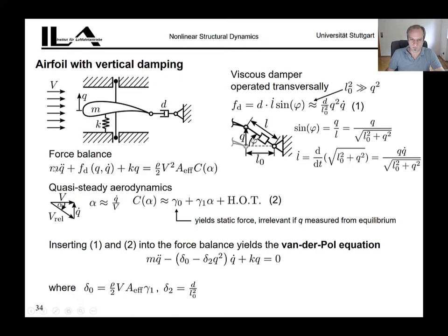And if we do the force balance here, we see that we need a balance between the inertia forces, the forces due to this damper here, the linear elastic forces, and the aerodynamic forces. Let's discuss the aerodynamic forces first. Here we just have the dynamic pressure, some effective area, and essentially the lift coefficient, which depends on the angle of attack.